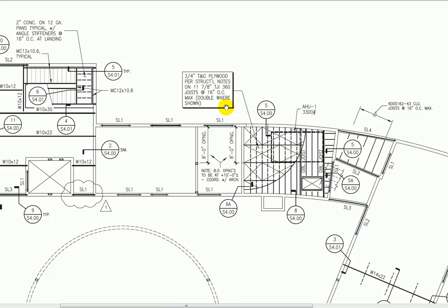So TJIs, we'd have to go back to the notes, but a TJI is a plywood I-beam. So now we have wood construction over here. So you can see, again, it's kind of cut away, but I see HU1 3,300 pounds. So this looks like it's supporting an air handling unit. Double joist. Just a little wood mezzanine.